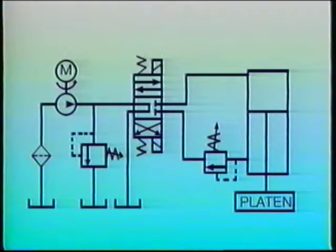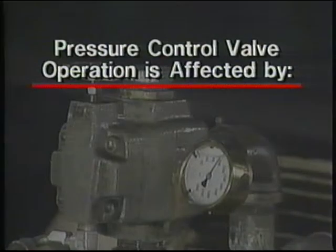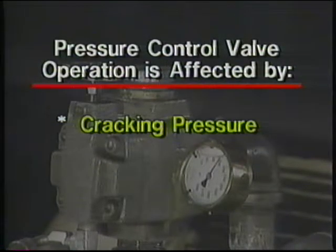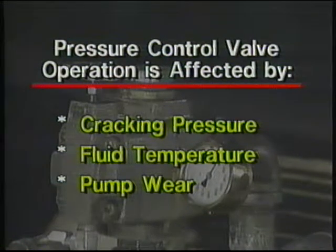Three factors are important for the correct operation of pressure control valves: cracking pressure, fluid temperature, and pump wear. Each may require adjustments to pressure control valves in order to maintain proper operation of the system. The pressure at which a normally non-passing pressure control valve begins to open, the cracking pressure, is less than the rated pressure of the valve.